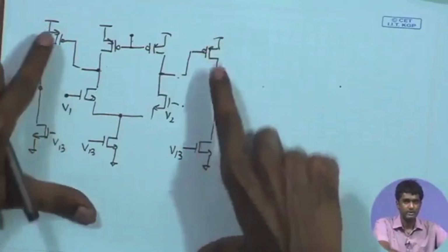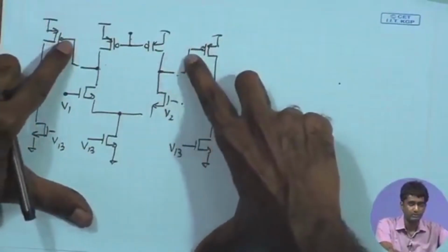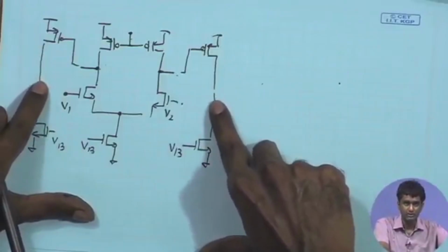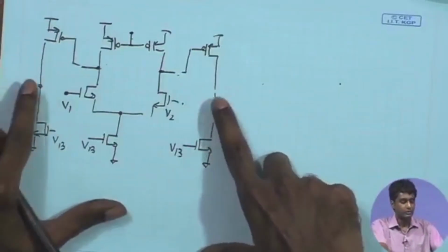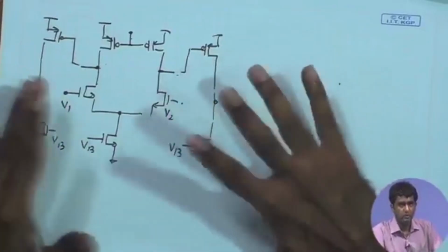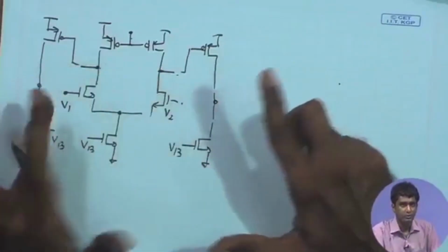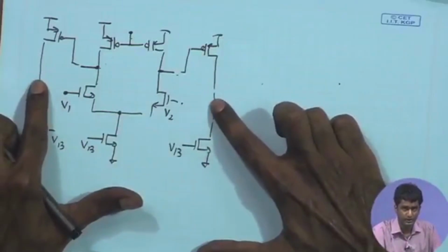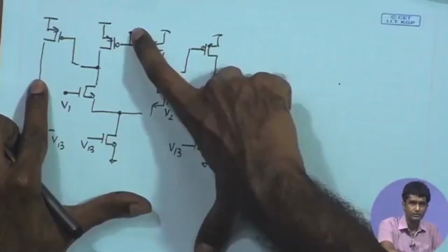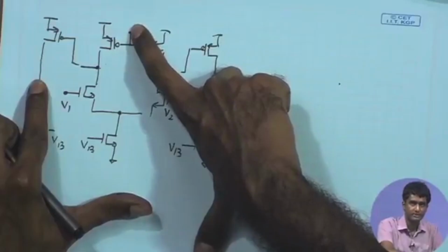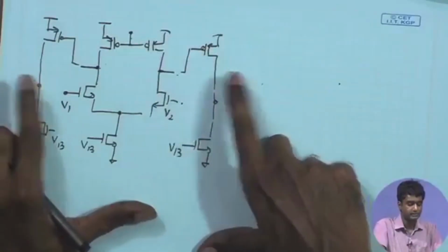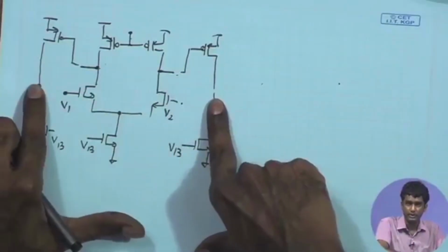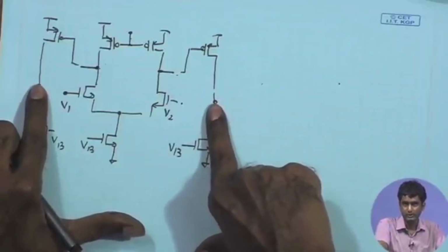So, this is a common source amplifier, input device, the load device, and therefore, the gain from here to the output is again Gm RO by 2, and these are also active loads, and therefore, we do not have a well defined DC point over here. So, now in this particular amplifier, how can we set the DC bias point for both the stages? One option is that we sense the common mode at the final output only, and then control the bias point of the PMOS transistor by the single error amplifier, assuming that it is going to set up the common mode level over here appropriately, such that the final common mode output over here is at the desired DC point. So, there is one option.